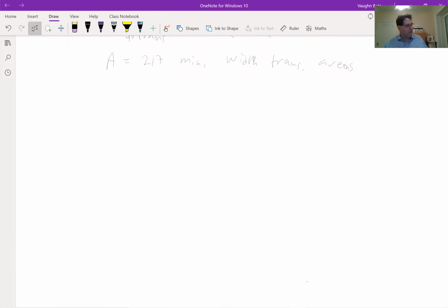So we've got our first order estimate of area, and that's an important area. So we wanted to estimate the area of our simple logic block and routing. Well, the logic block was basically a 4 input lookup table. We just estimated its area. Okay, but that's not everything. So we've got the LUT. Now we need to look at how it connects to the routing.